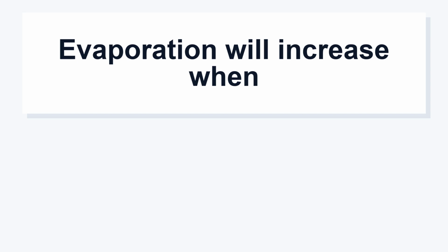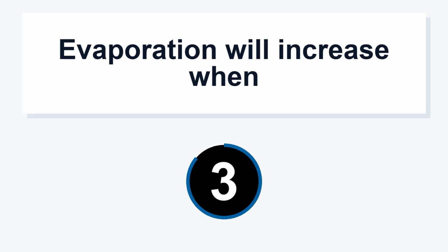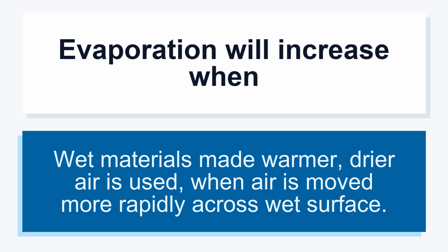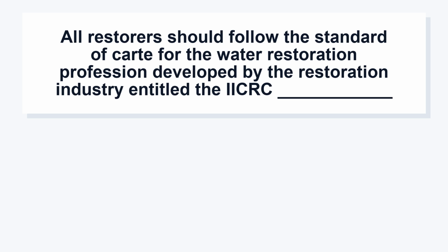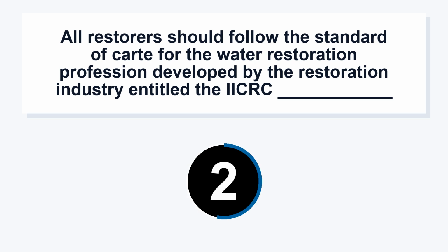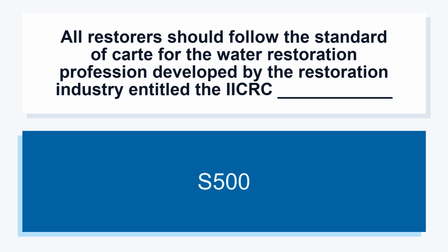Evaporation will increase when wet materials are made warmer, when drier air is used, and when air is moved more rapidly across the wet surface. All restorers should follow the standard of care for the water restoration profession developed by the restoration industry, entitled the IICRC S500.